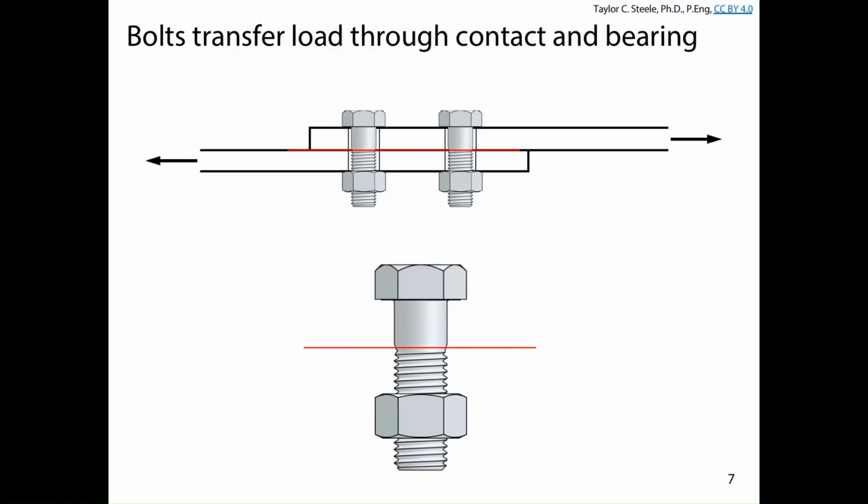So the way that bolts transfer force is primarily through shear when they're arranged this way. And generally the reason for that is, well, we've got two members that are lapped together. Perhaps one side is the gusset plate, maybe the other side is a flat bar. It doesn't really matter what they are. But through those members that are carrying force longitudinally through them, we poke some holes and throw some bolts in those holes such that the bolts are transverse or perpendicular to the applied load.